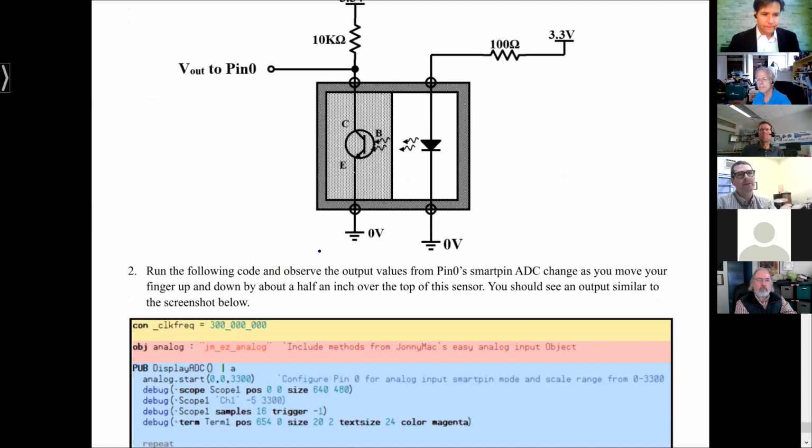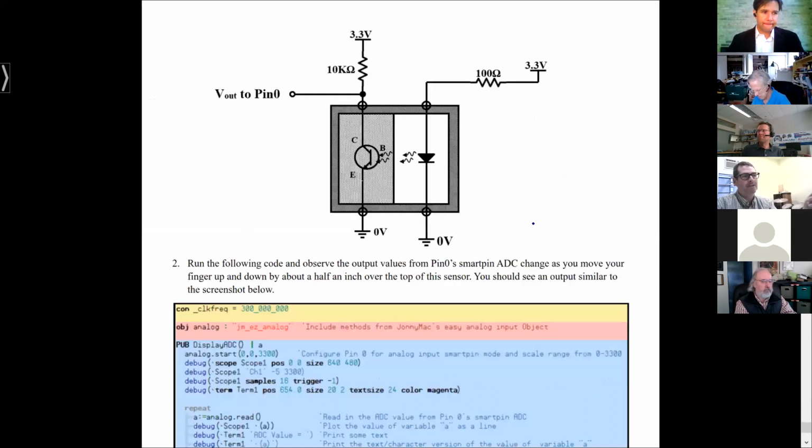One guy who's been on here said that he was using the level comparator mode, which is in the smart pins, to do successive approximation. And he was getting way beyond the bandwidth of what we're getting out of the Delta Sigma ADC. Interesting. How many bits? Is that 8? It's 8 bits. It's really probably 7 really good bits.